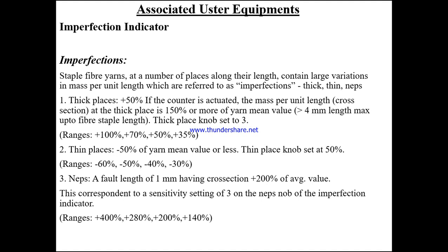After that, we have discussed the various measurement methods of irregularity in textile materials such as yarn, roving, and sliver. Among those measurement methods, one of the most popular instruments is the Worcester evenness tester. We have discussed the principle of working of the Worcester evenness tester, which is the capacitive method. Now we shall proceed further.